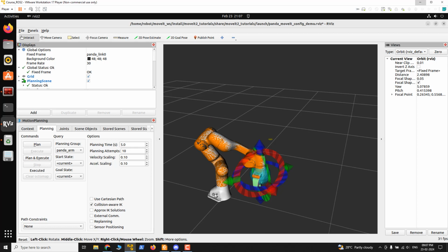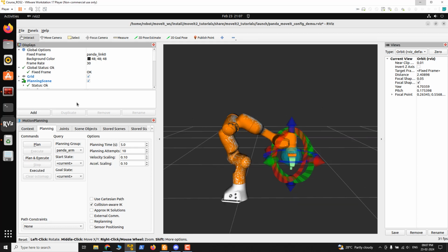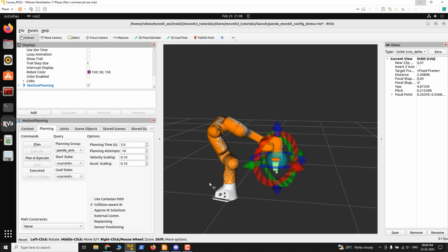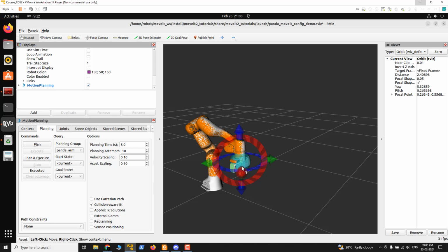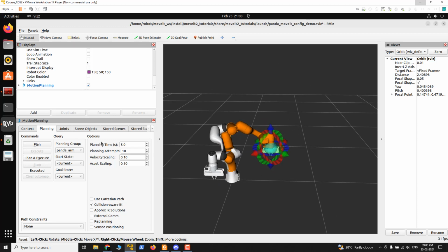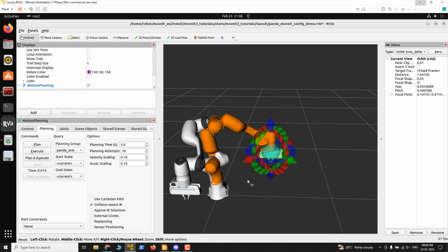These all things are TF only. From the TF, you can find the final angles. But it has to execute basically. What I am trying to say is, when we give the goal position, it is creating the trajectory, right? So when we execute this trajectory in the robot, you can compute the final joint angles using the TF or using the joint state.